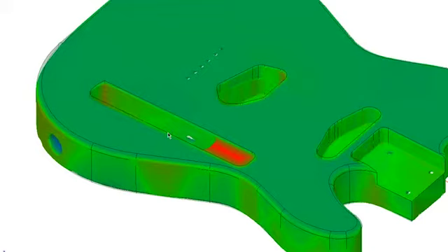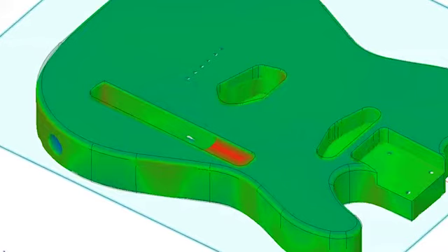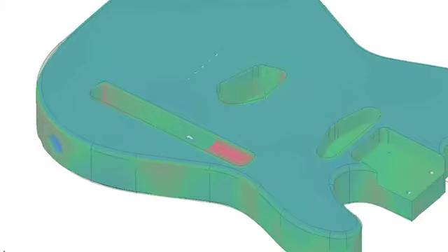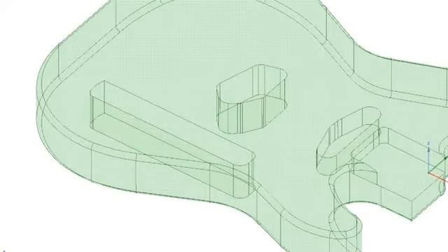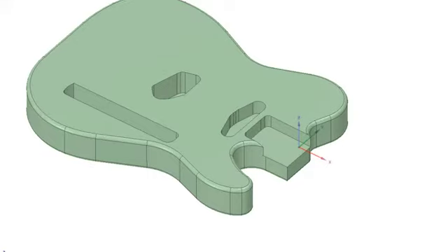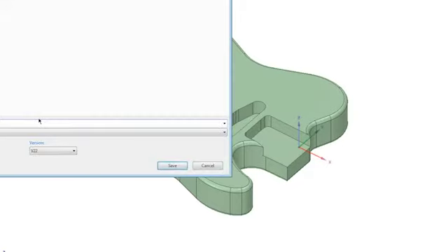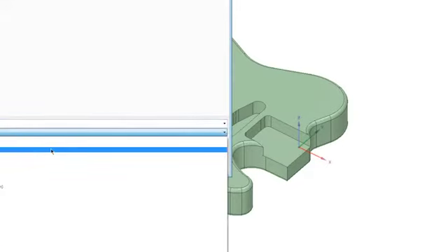Okay. Once you create a solid model in Spark, can you export it as an STP or an IGES file, or can you use it in other CAD software? Yes, you can. So if I turn off my mesh on screen and turn my solid on, I can go to the Save As, and I can save as a variety of different interchange formats: Parasolids, STEPs, IGESs.